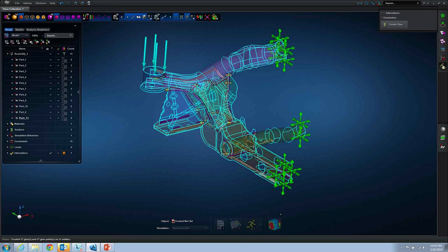In the bottom area, what you see is new in Cheetah. This is what is called analysis readiness. Creating the model, checking the model, creating an assembly representation of the model, and running the simulation is as simple as clicking 1, 2, and 3. That's what you see right in the user interface as well. In a given assembly, you can do this simulation either at a single part level or at a multiple parts level, or you can create a subassembly out of this one and move the parts into that subassembly, or you can analyze the entire assembly.